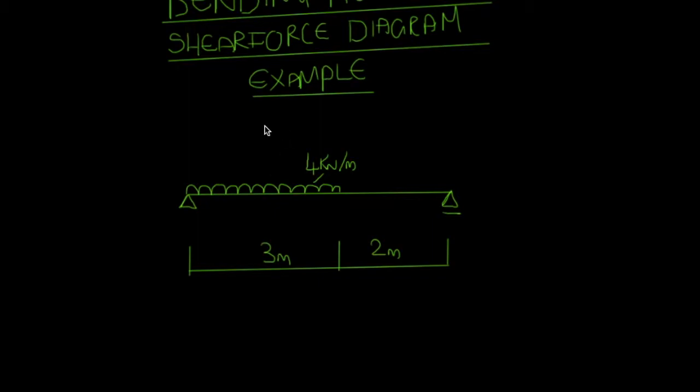If you're not familiar with how to identify a simply supported beam, just a quick rule of thumb is you identify the number of reactions. So we have a vertical reaction on this pinned support, we also have a horizontal reaction, and we have one vertical reaction here. We'll call this side A, and we'll call this side B, and this will be AY, this will be BY, and this can be AX. That's a total of 3 reactions for one member, so that means this beam's in equilibrium.